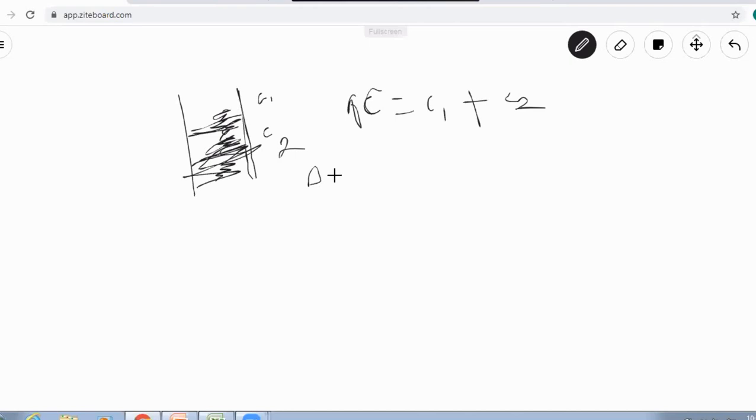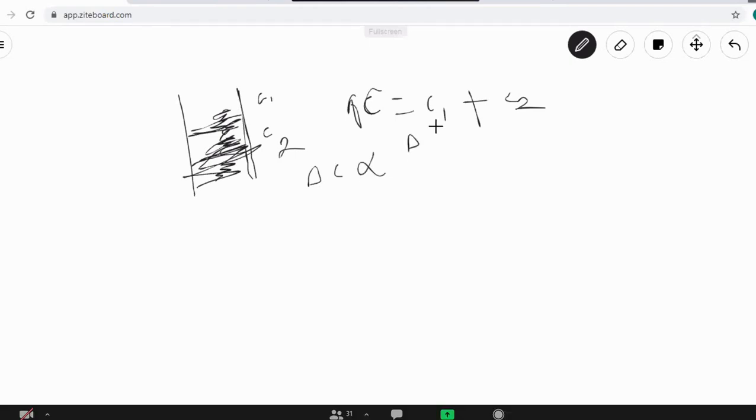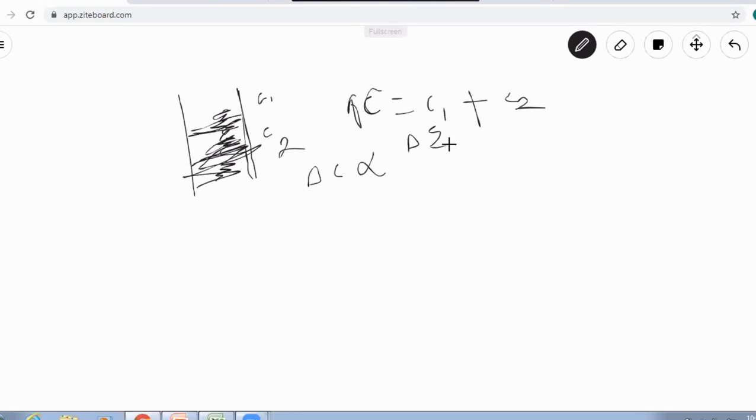That is del C. So del C is proportional to the change in the dielectric constant. So del C is also proportional to del epsilon. That means if we vary the dielectric medium, if we increase the level between these two conductive plates, then automatically the capacitance value increases. Then we can calibrate the capacitance value and read it on an indicator meter from the outside.